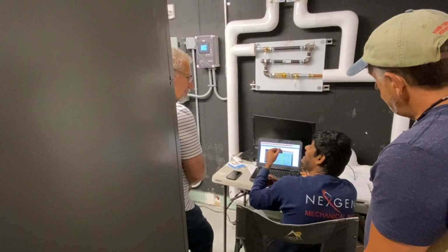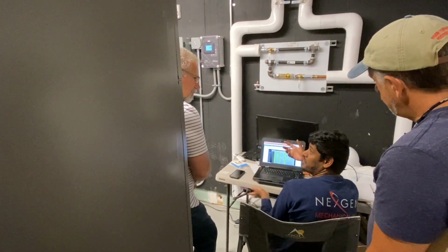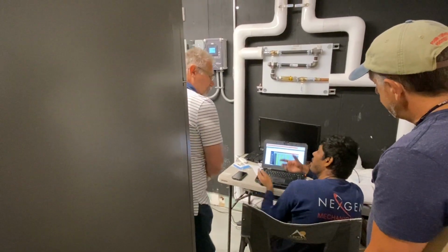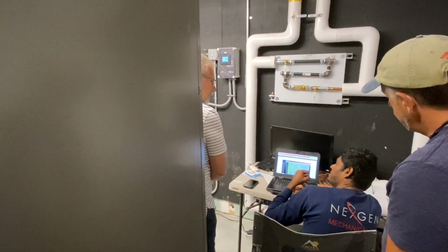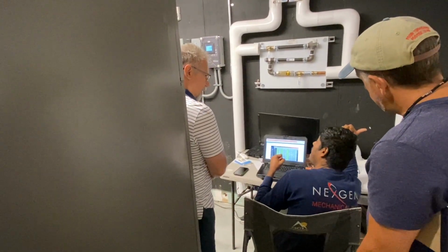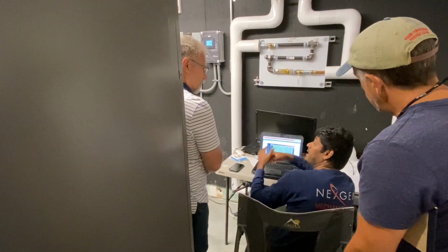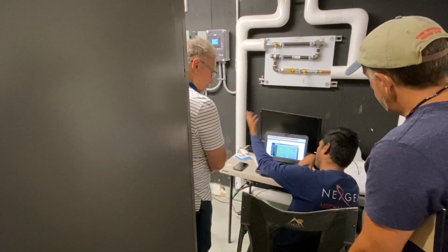But it is based on my VAVs' input, which is the average space temperature. I get the average space temperature input, I calculate based on my outside weather, and I calculate based on my next schedule. Then I decide, okay, I want warm up, I want cool down.